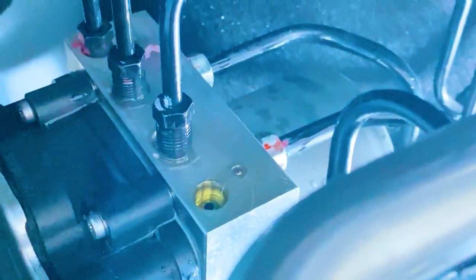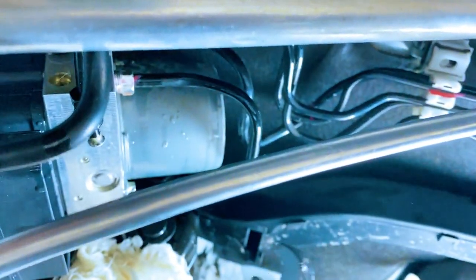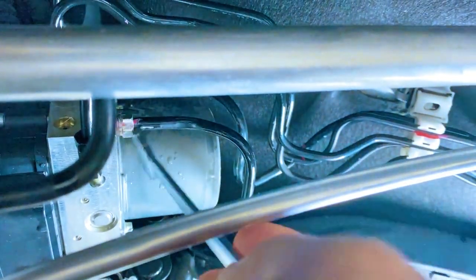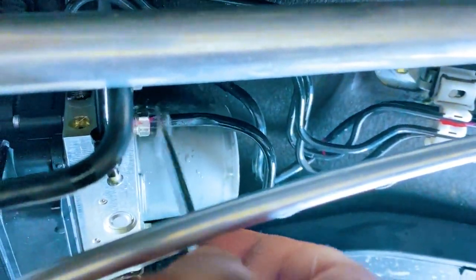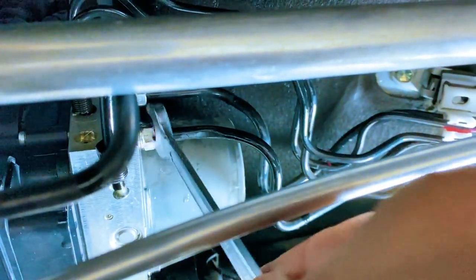Understanding the brake actuator. Before removing the component, we need to understand what Toyota calls the brake actuator assembly. Many people simply call this component the ABS pump. But technically, it is much more than a pump. The brake actuator assembly contains the hydraulic control unit and important electronic components of the braking system. The ABS motor relay is built into the brake actuator assembly.